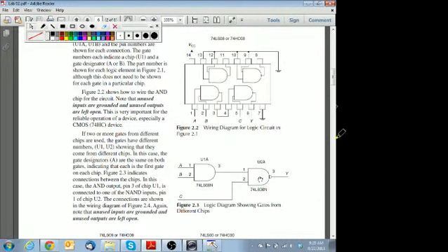It has two different type gates. They normally do not, that I know of, combine two different gates in the same package. Normally, when you get a package, you'll have 4 AND gates, and another package you'll have 4 NAND gates. So this tells you right away that you're going to have 2 separate IC chips. And it tells you the pin numbers.